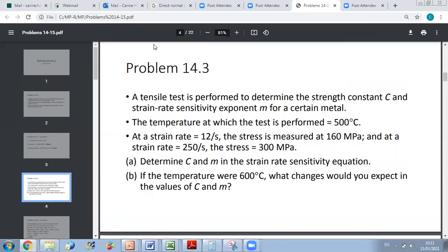So here, if you have, for example, a compression operation, then the plates are compressing your specimen. The height will be reduced. At each instant, the strain rate is the velocity of the approaching. So if I draw the figure, let's say you have a specimen between two plates. You can have a compression test or a tension test. If you have a tension test, let's say, at any instant, if I fix the velocity, what will happen to the strain rate?